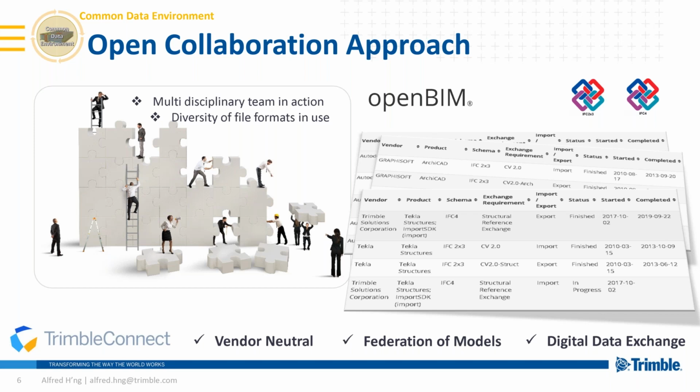It doesn't matter now if architects, engineers, and contractors are using different BIM authoring tools. And the object attributes, identities, and relationships are codified in the IFC schema. Properties and attributes of the objects are retained and not lost in IFC exchange. And hence it makes workflow integration possible.